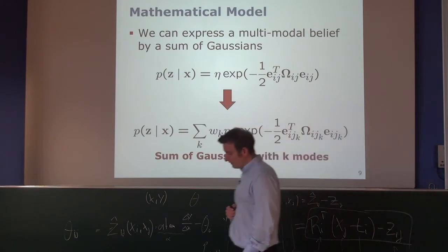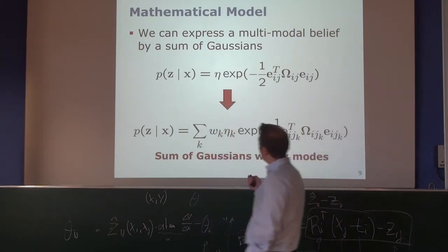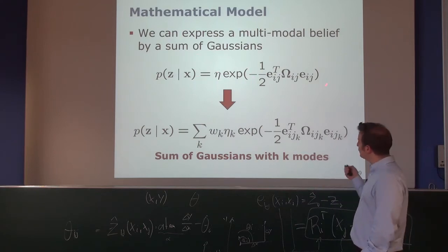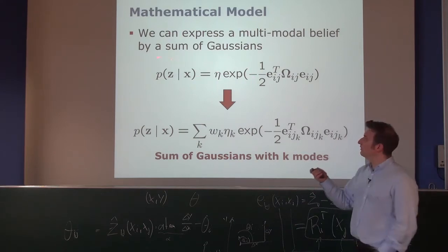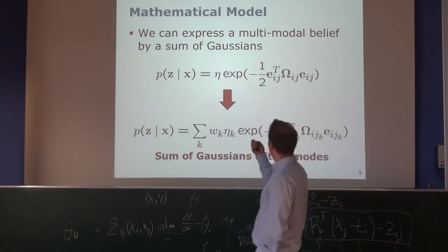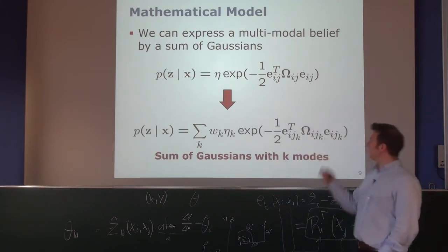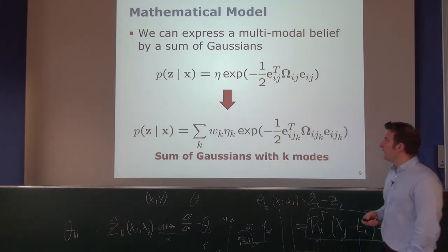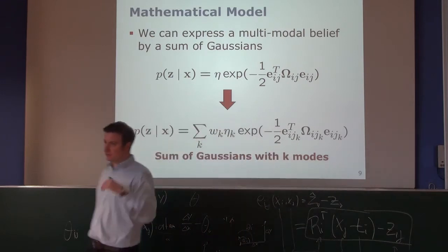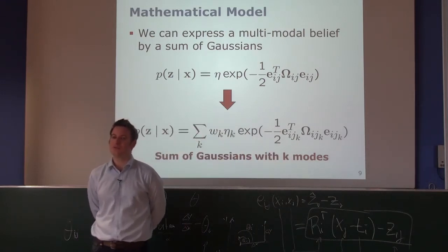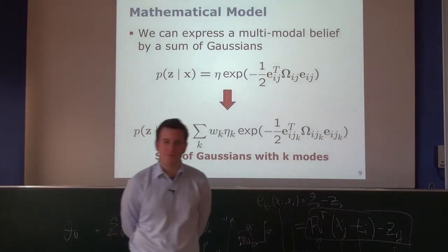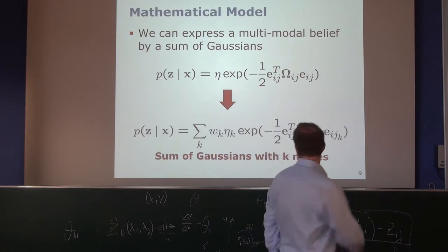The problem that we actually have is if we look to an individual constraint. So the likelihood of an observation given the current configuration of the nodes was a Gaussian distribution. So that's what we had before. If we now say, okay, we would like to have simply a sum of Gaussians in order to have a multimodal constraint, so some of those constraints are multimodal, we simply have a sum of Gaussians. Right? That's the first attempt to solve this problem.